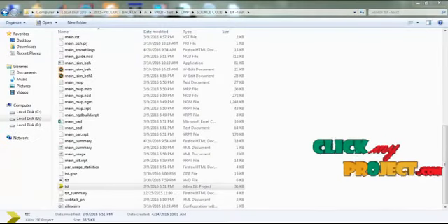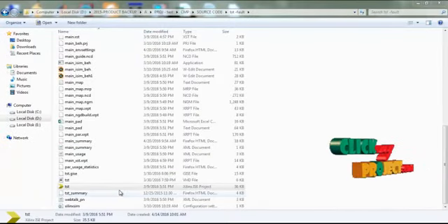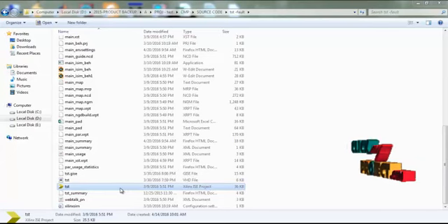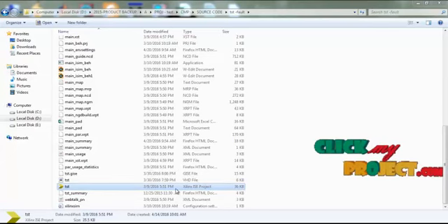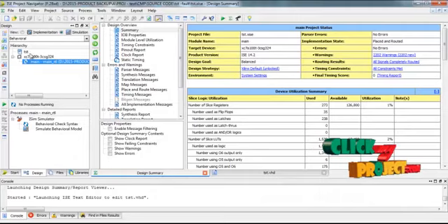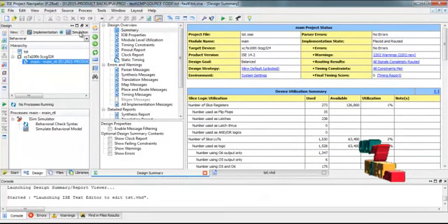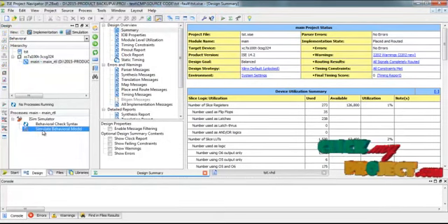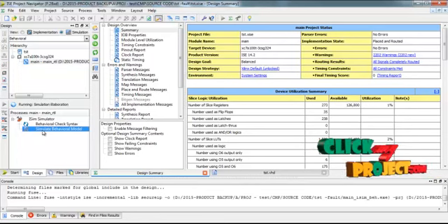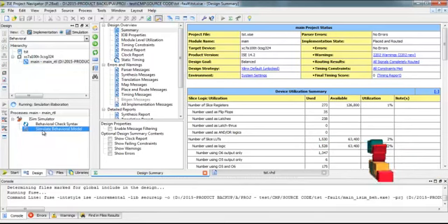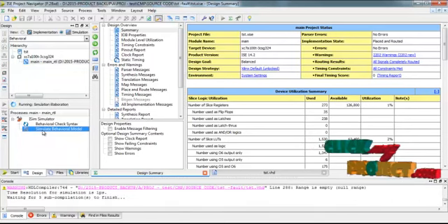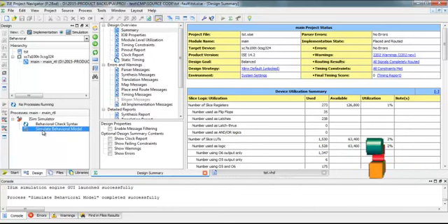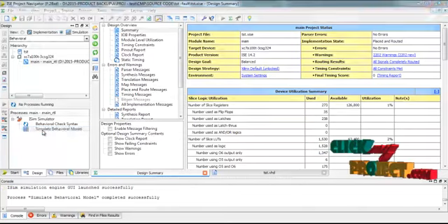Finally, we see the output for the product. These are the test functions for the Xilinx ISE project. Just double click the ISE project file, then open the software file, then we go to the simulation process, then select and simulate the behavioral model to be run. This process runs the inputs passed to our architecture, and the present output and the error detection and error correction processes are all displayed in the simulation.